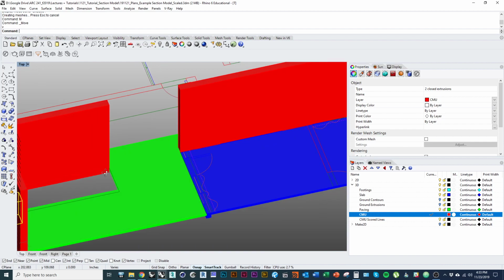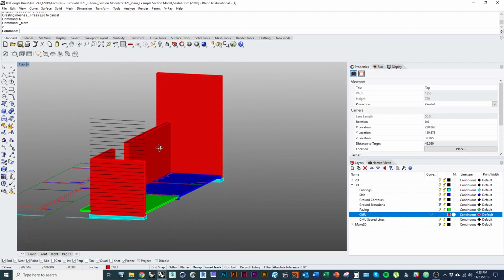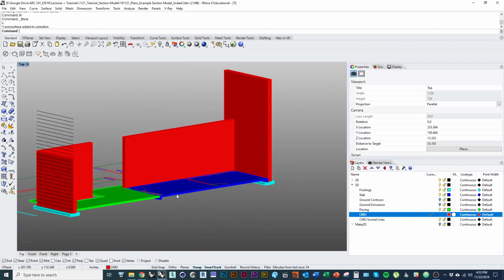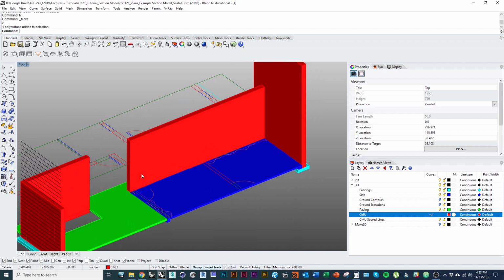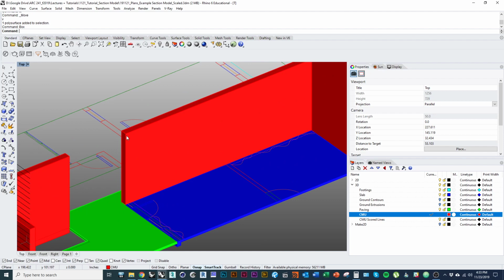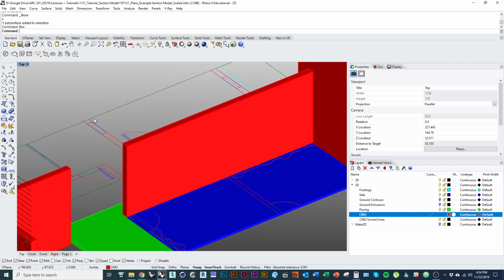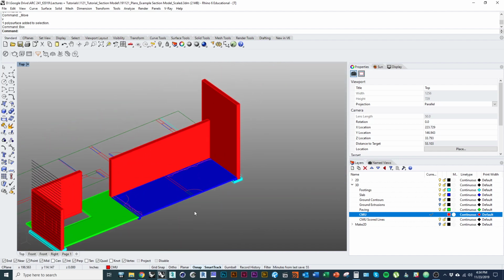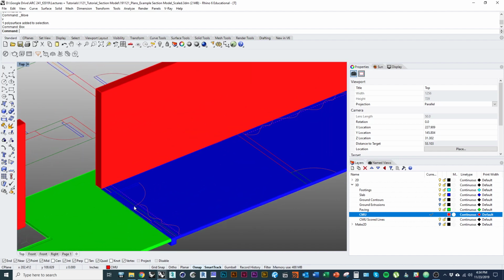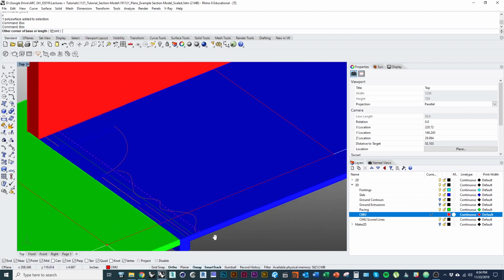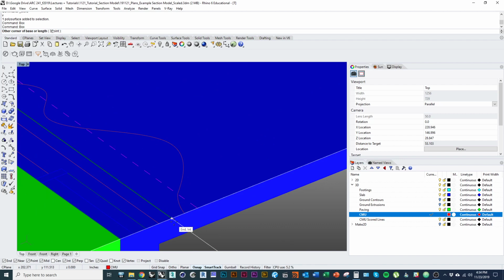Now I want to do the same over here, so I should mention, with this wall we're actually going to have an opening here. I didn't model it before, but there will be a couple of courses of CMU above this wall, because this is a load-bearing situation. The second floor units sit on this structure. So I also need to model a couple of courses of CMU. And let me just do it roughly using the plan, and then I'll scale it.